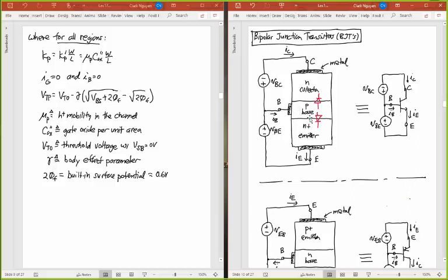So for example, if I take this junction here, which I can call the collector base junction. So this N type up here we call the collector. The P type we call the base. This N plus down here we call the emitter. And the symbol for this transistor looks like this. It's a lot like the MOS transistor, but I don't show a gate because it really doesn't have a gate. It just has a terminal going straight to the P-type base. It's got a terminal going straight to the N-type collector and a terminal going to the N-plus type emitter here.